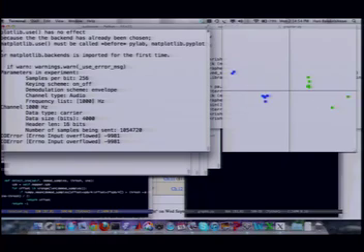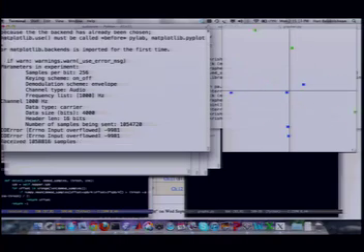You can see that what's going on here is, if I'm silent, the points get demodulated at +1 and -1 that correspond to the top and the bottom of the waveform. And if I make a noise, the effects of noise get visible. And in fact, you can see that sometimes the guy on the left goes to the right and vice versa. Okay? So that's actually a very visual effect of what noise does to your transmission.